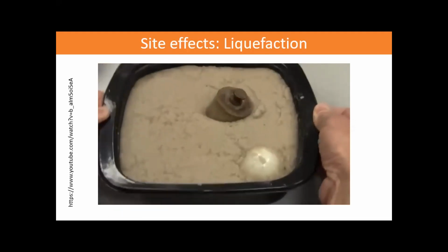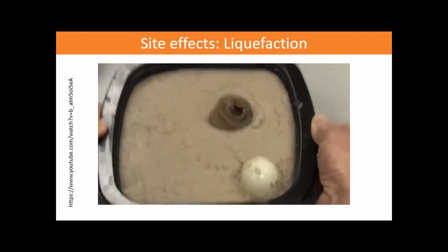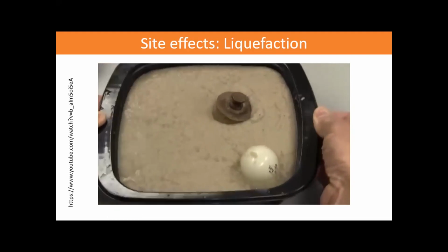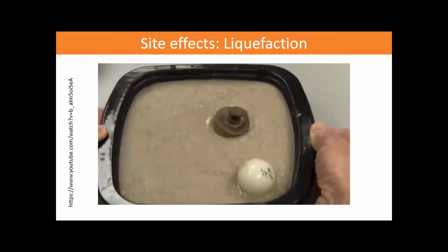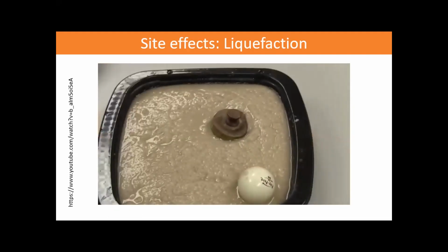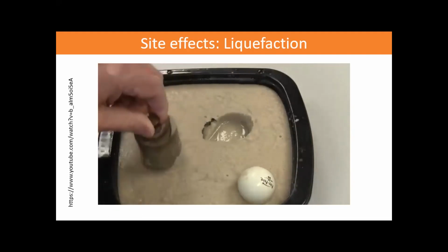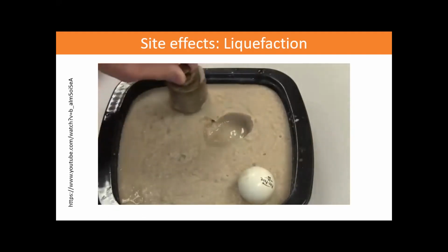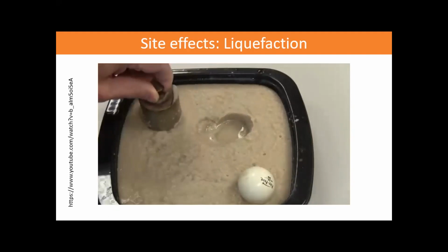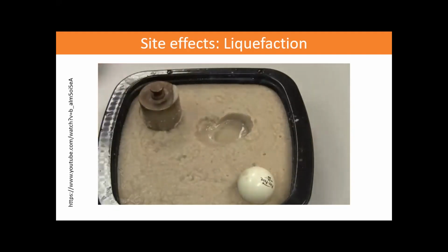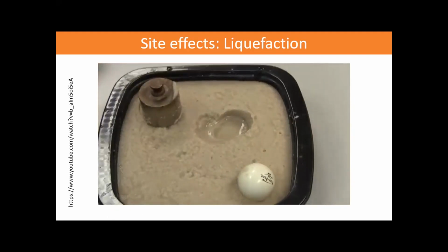So if you think of just a coastal system, they have stuff buried like pipes, represented by that ball to the right. So as you're shaking, you're bringing subterranean buried things up, and with weight on top of it, you're kind of settling it out and bringing it down. So this is what's known as liquefaction, which is where these solids that are saturated end up behaving more like a liquid whenever you introduce shaking to it.